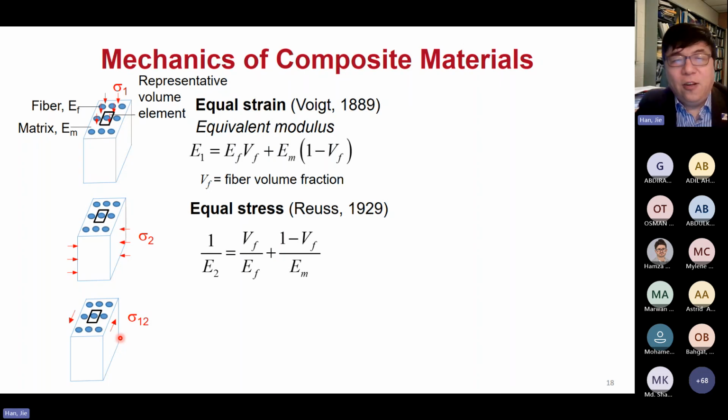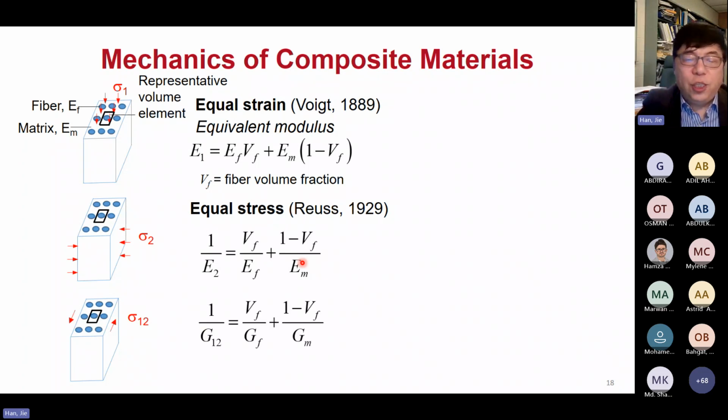The formula looks like that, though it's not exactly like this one. But the modulus here is basically this replacement ratio, this fiber modulus, this soil modulus, and I will show you an example of how that affects the real number. Now, if we're dealing with shear, the formula is similar to this one. This is called the rule of mixture.